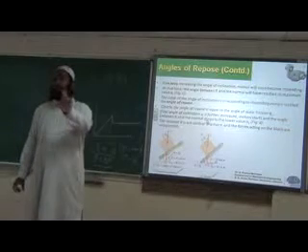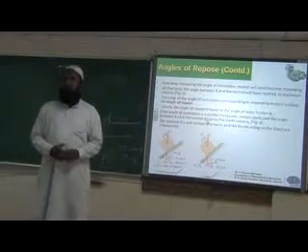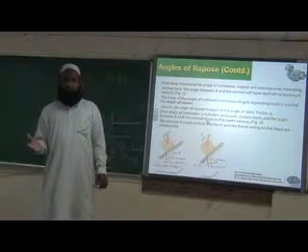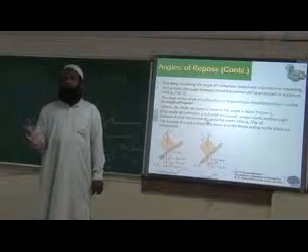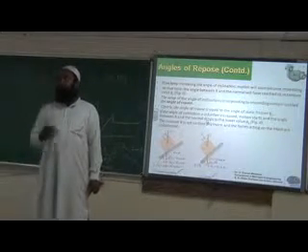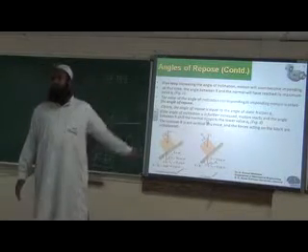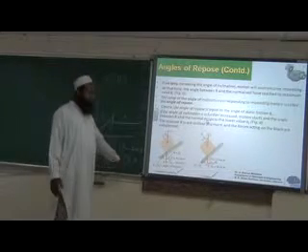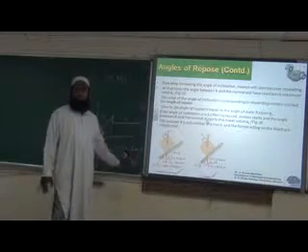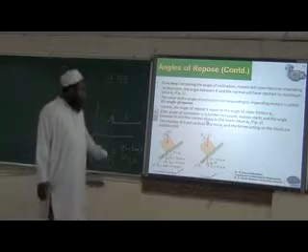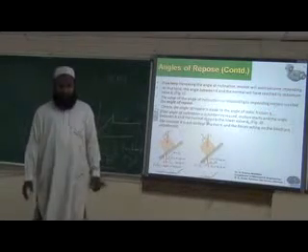So that limiting angle is called angle of repose. Okay. So if you tilt further, if the angle is increased further, the body will start moving. It will be impending in motion. So the limiting angle is the angle of repose. Angle of repose and angle of friction are same. Okay. For our simple body, if you consider.